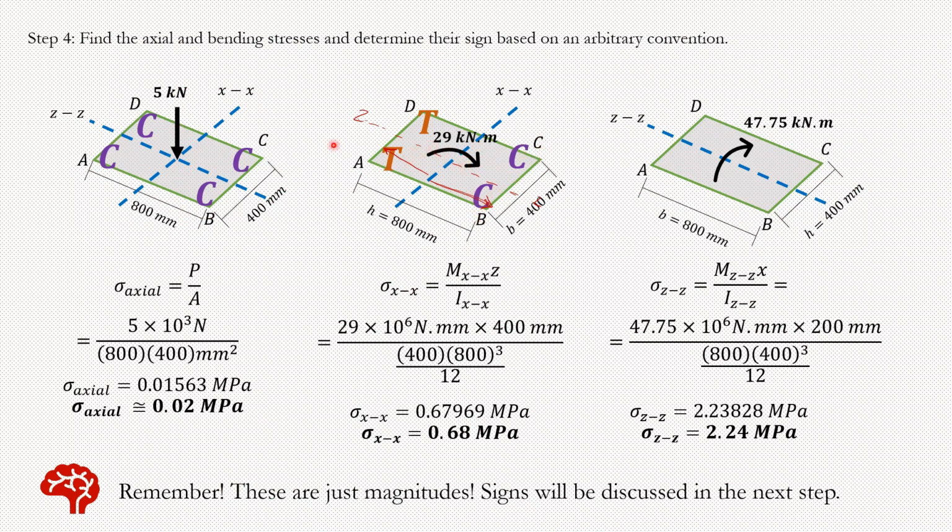And I'm pulling from A and D. So I'm pulling from A and D and pushing to C and B. Any push in one direction is compression. If I'm pulling from something, that is tension. One easy step to remember is that whatever direction the arrow is going, that side is the compression side. That's why C and B are compression and A and D are tension.